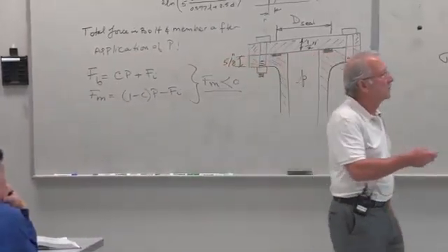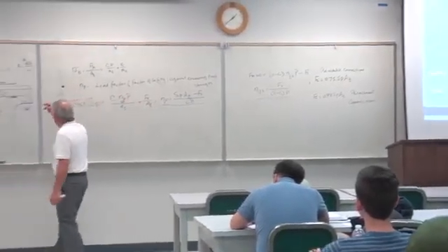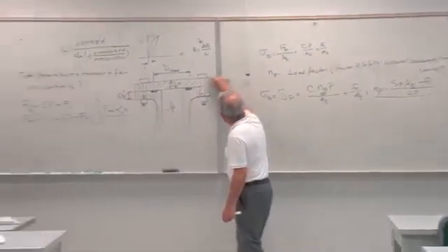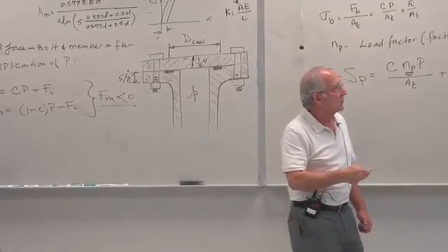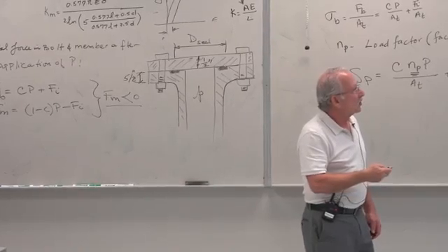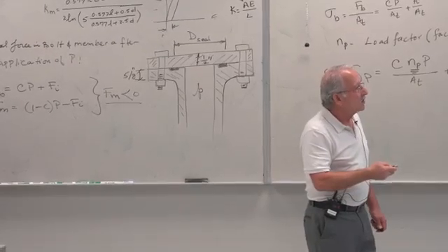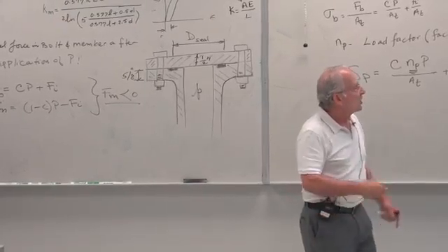So here it is. Grip length. That's from here to here. The sum of these two thicknesses. There are no washers in this case. 1.125 inches. And nut height is 7/16 of an inch from table 831.